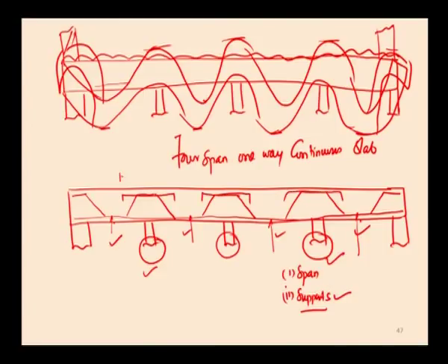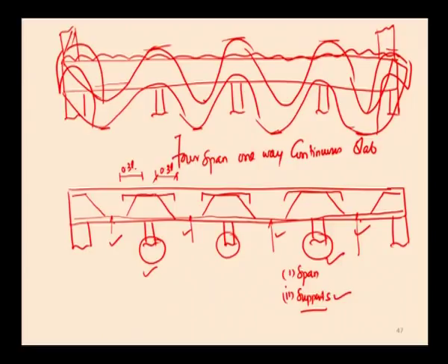The length of this reinforcement should be 0.3 L on either side of the face of the support. This is an extra reinforcement which has to be provided at the top, exactly over the bottom straight bars.